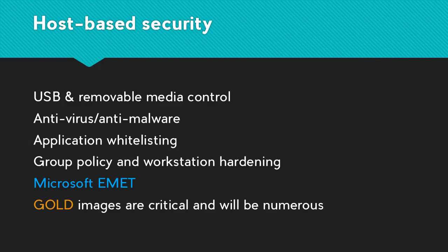Your gold images, so your standard by which you build systems. You've got those in enterprise IT, but you're going to have lots of them in industrial IT because you're not going to have a general purpose workstation. You're going to have an engineering workstation, an operations workstation, and you may have an HMI system. So just understand, you should build the gold images to the proper patch level and the proper configuration that the software requires. You're just going to have a lot more of them than you do on the enterprise side.